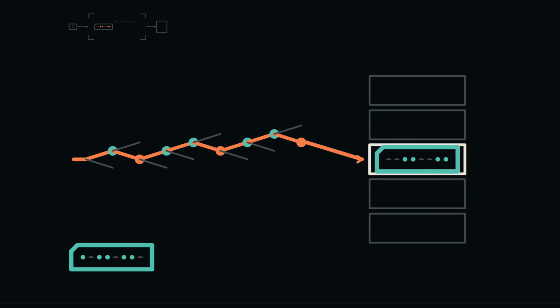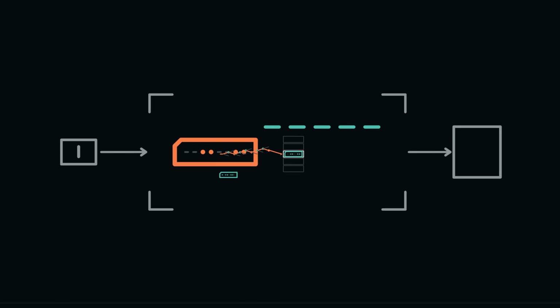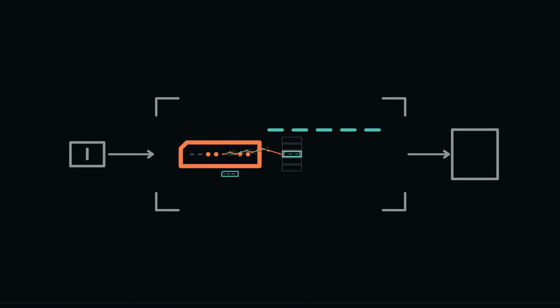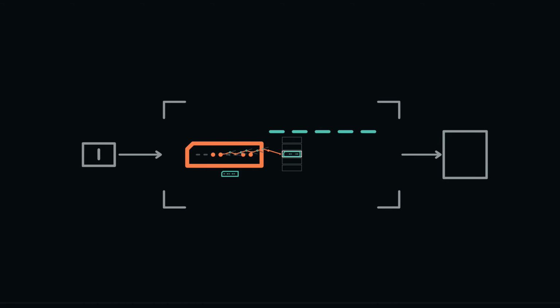The growing machine can now answer which one. Address bits express a compact pattern. A decoder converts that pattern into exactly one active selection. Address wires choose. Data wires carry a byte. Storage cells preserve it. The house number comparison has served its purpose and stops before the mechanism. Decoder logic performs the selection without reading a label.